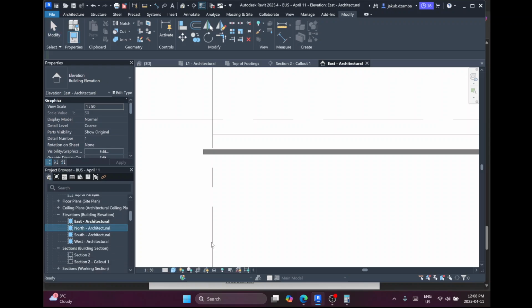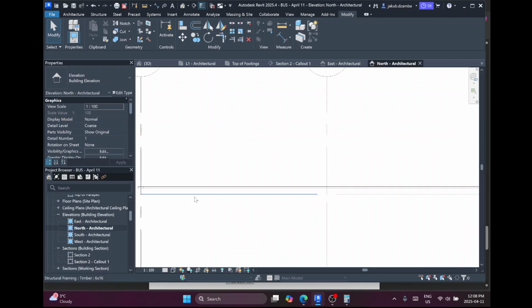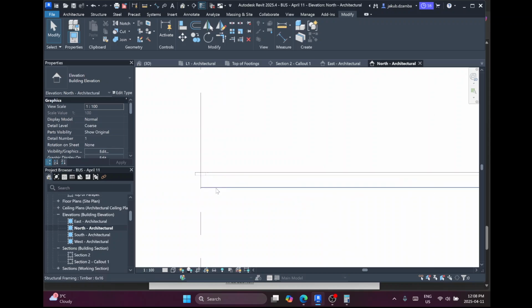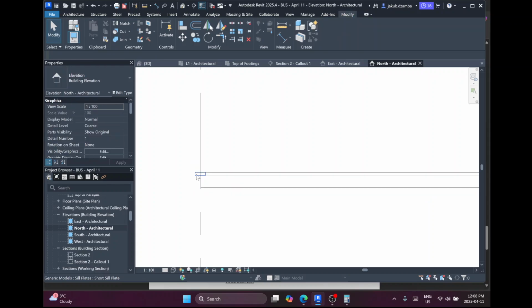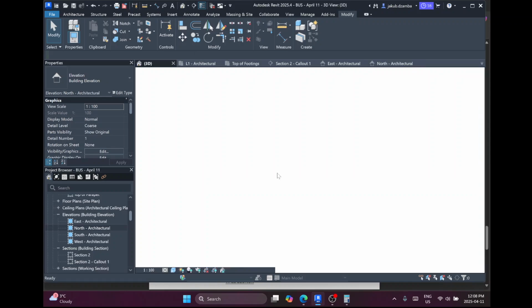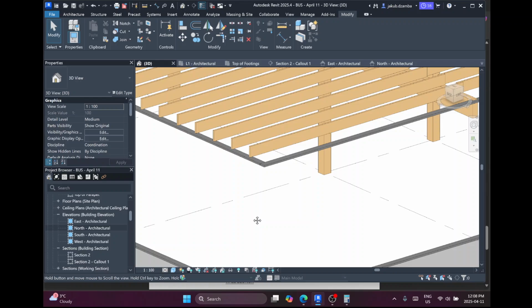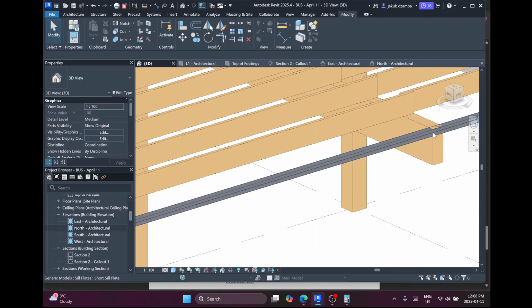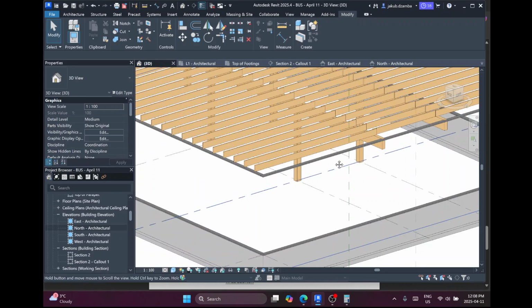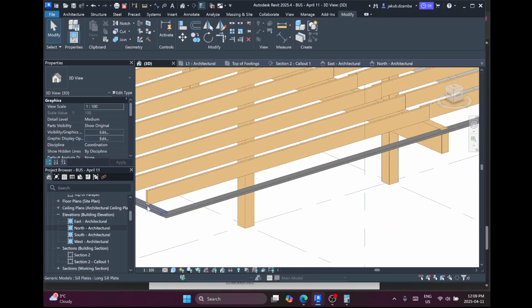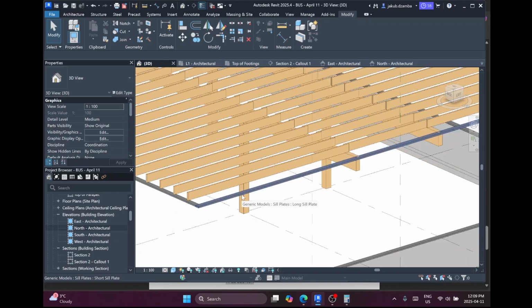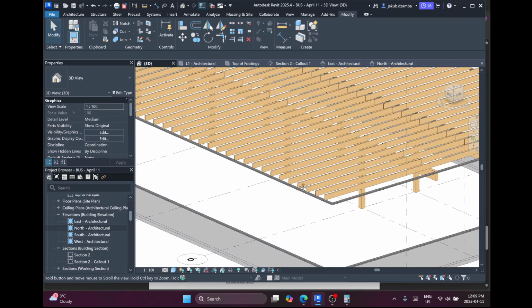Let's try the other direction. What is this? Timber. Sill plates. Strange. Okay, so it intersects. Yeah, we have to resolve those columns at the end. I think these beams at the end, you may have to put another column on it. But I think in terms of this resting on the right thing, we're in a good place. So let's continue with the framing.